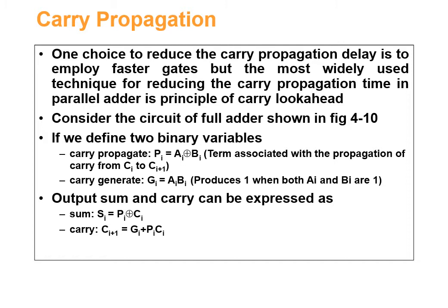Another solution is to increase the complexity of the equipment in such a way that the carry delay time is reduced. There are several techniques for reducing the carry propagation time in a parallel adder. The most widely used technique employs the principle of carry look ahead logic.